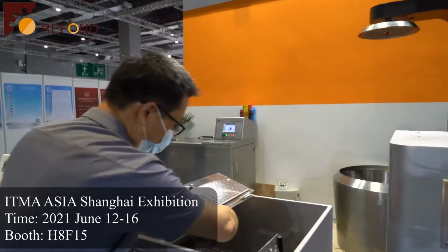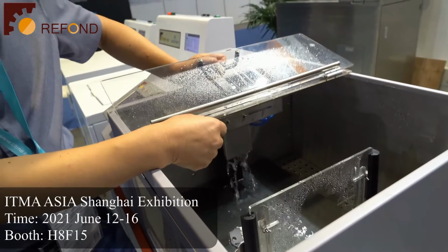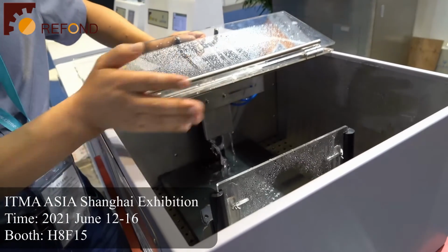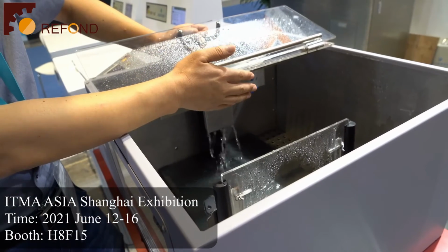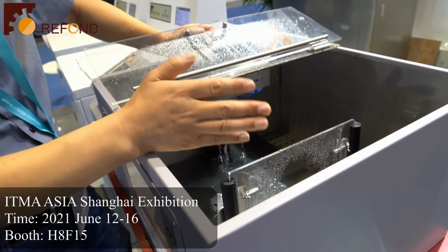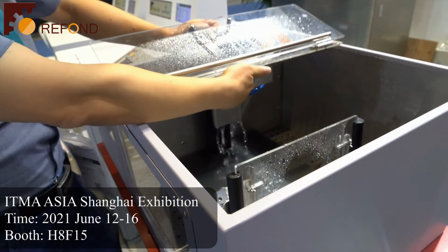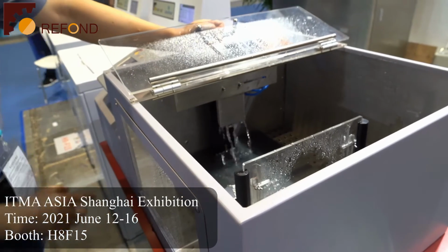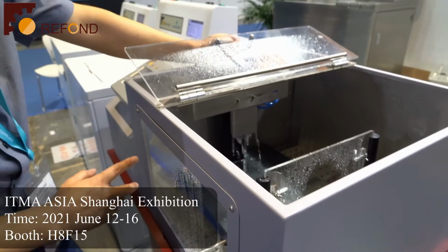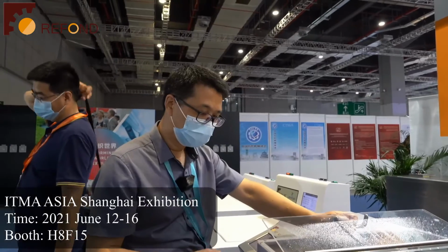This is the blocking plate, which can block the water after the test is finished. This blocking plate is automatically controlled by the compressed air. But now here, there is no compressed air in the exhibition center, so I move it by hand. The blocking plate makes it possible for the water to circulate continuously. The continuous water circulation makes a stable pressure, so the machine can control the water pressure stable.